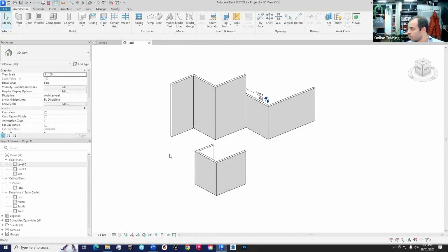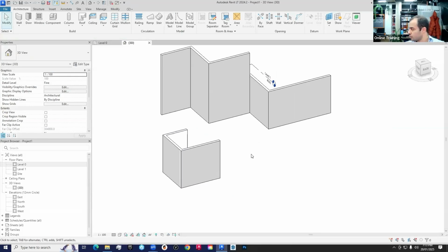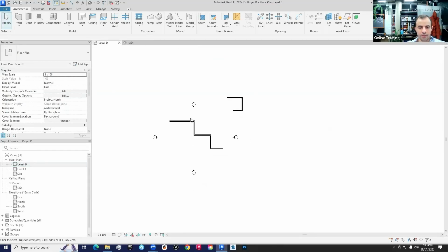Okay, so you can do it on the fly, or you can also change the properties later after you finish things. Of course, it's better to edit things on the fly, where you know what you're doing before doing it. So you think before you draw, because you might forget to change things after you model them. You might forget that this wall was following a wrong height or something like that. So it's usually a better practice to check the properties of what you draw before you actually go ahead and draw it. Okay. I'll get back to level 0.